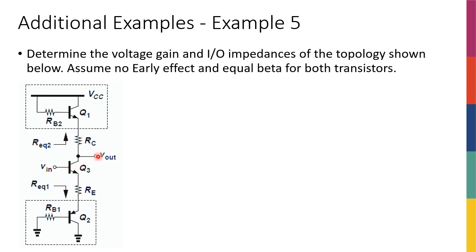It's just a 1-stage amplifier, and the amplifier is common emitter. I can see that because input is connected to the base, output is taken from collector, and it's a common emitter with degeneration because I have some stuff at the emitter, right? Now, what's the point of the other 2 transistors?